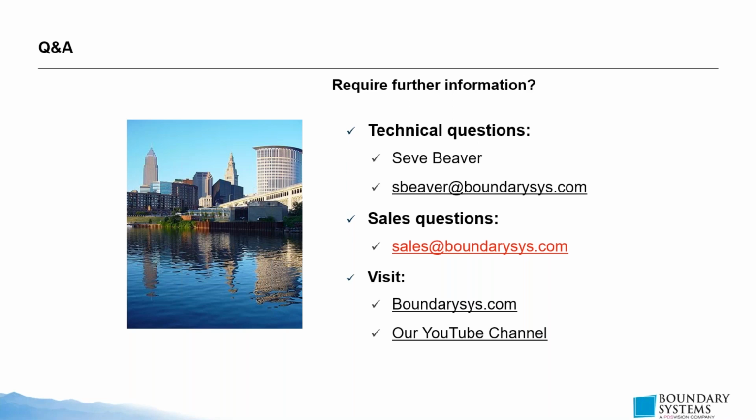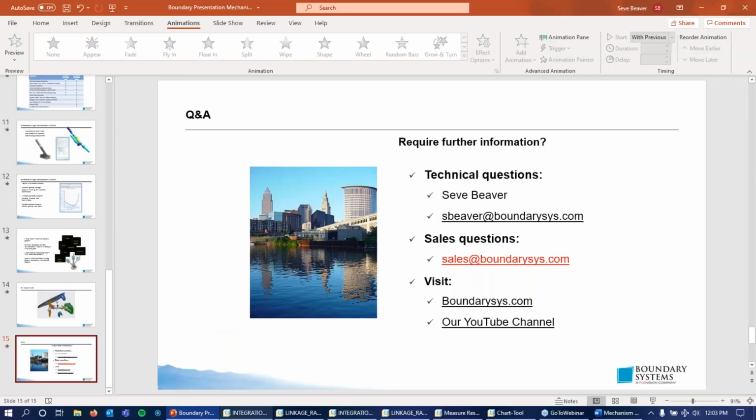The answer is yes. Besides going on PTC's website and seeing your company's licenses and which particular computer they're assigned to, which is kind of a long way, you can go into your Creo files and run a PTC status. I can show how to do that real quick.